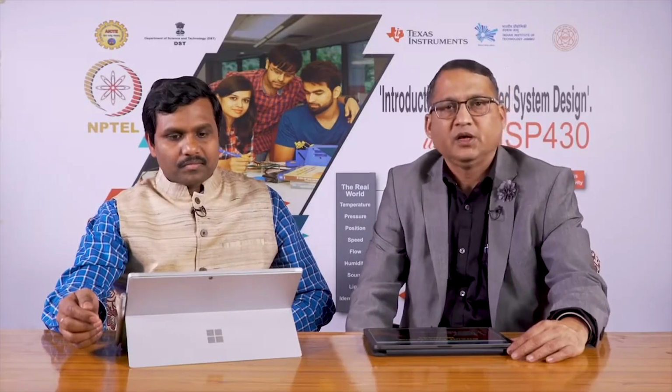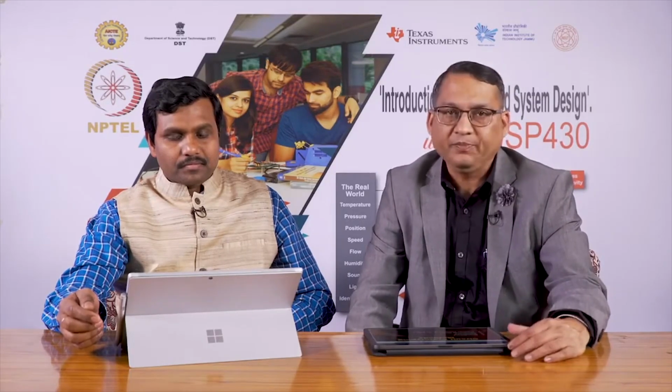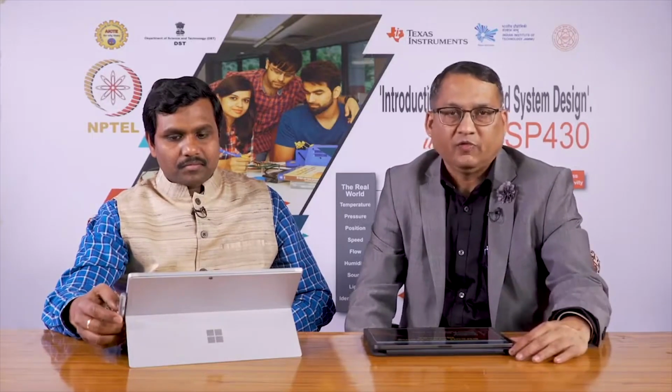The second method is closer to the actual final professional implementation, and that is called using a zero board. Zero board is nothing but a general purpose printed circuit board which has holes at regular intervals where you can insert your components and solder them. Of course, this is not as close to a custom printed circuit board, because you have to make do with whatever holes are available and fit your components.